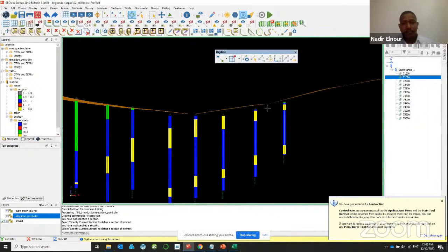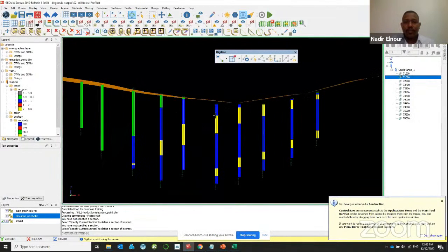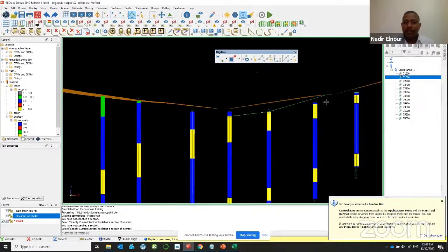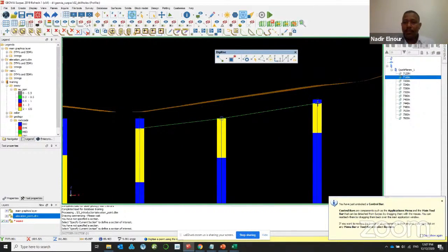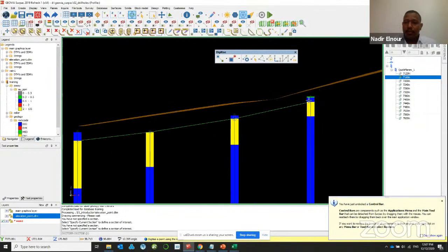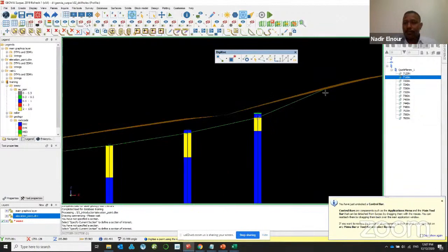In order to digitize, you can snap to the points, number 2, and then you come here, snap to this point, then this point, then this point here, then here. And then from here, if you have mapping, you know where this vein ends. You can press 4 and snap to the topo, then 1 again.